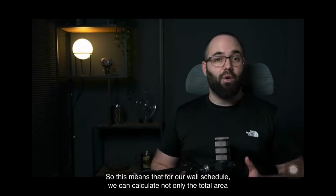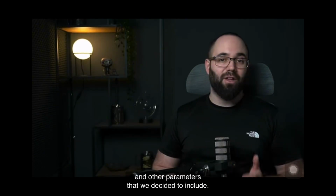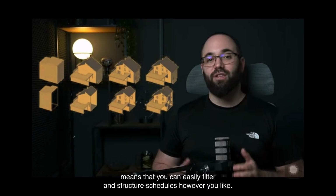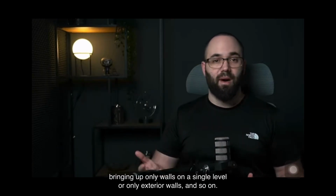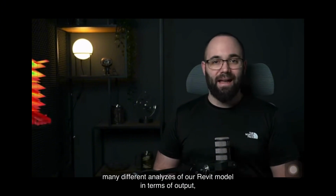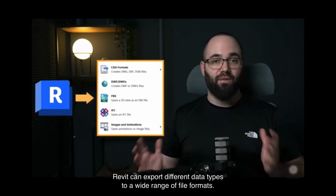So this means that for our wall schedule, we can calculate not only the total area or volume of the walls, but also their total weight, cost, and other parameters that we decided to include. This all being part of a building model means that you can easily filter and structure schedules however you like. For example, bringing up only walls on a single level or only exterior walls and so on. You can also use all of this data that's built into the model to run many different analyses of our Revit model. In terms of output, Revit can export different data types to a wide range of file formats.